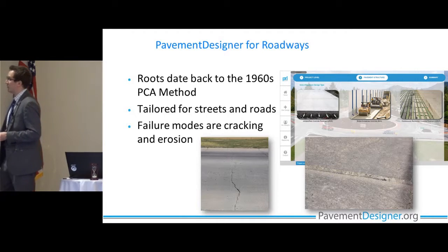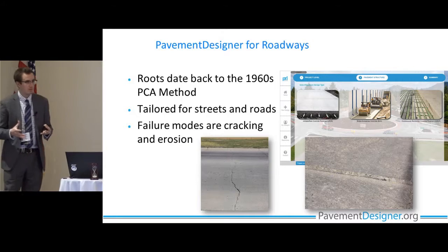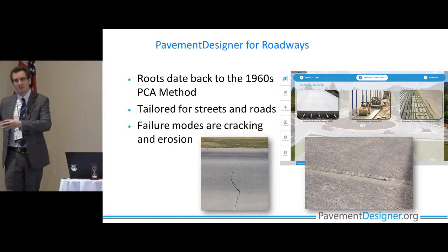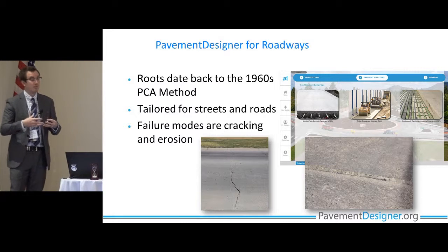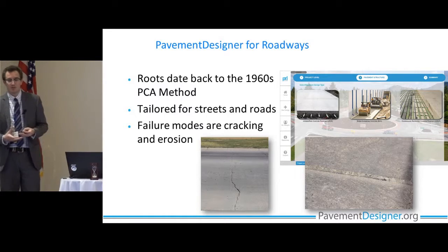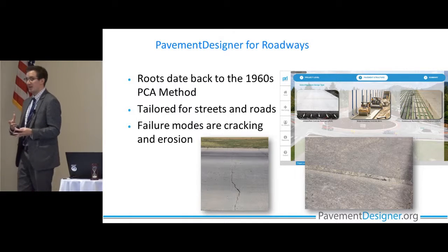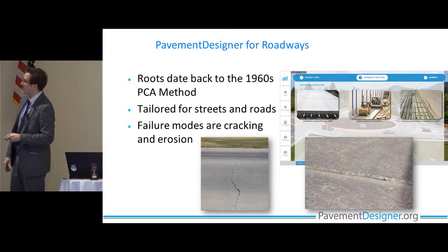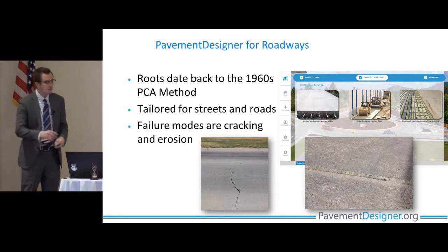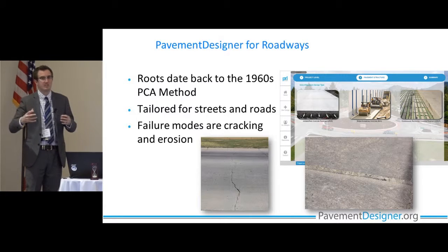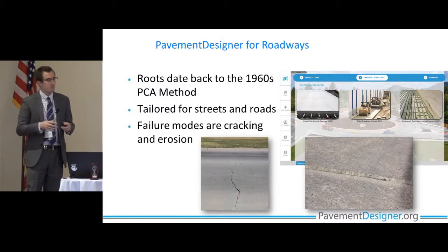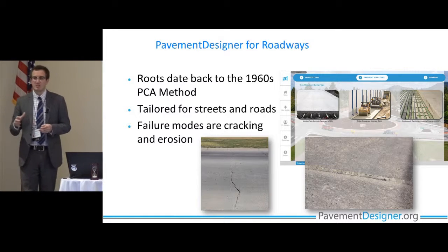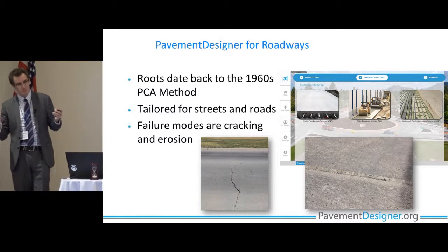Now one of the big benefits of moving away from AASHTO 93 towards Pavement Designer or Pavement ME is that each of these methodologies are mechanistic empirical. We're not just evaluating it based on a road test. We actually have mechanics of materials built into the design program. And so that's one way that Pavement Designer and Pavement ME are fairly similar. So failure modes within Pavement Designer are cracking and erosion, similar to faulting. So we're trying to improve how we're considering failure within the pavement design, very similar to Pavement ME. Again, moving away from the AASHTO 93 procedure of just considering a serviceability index.